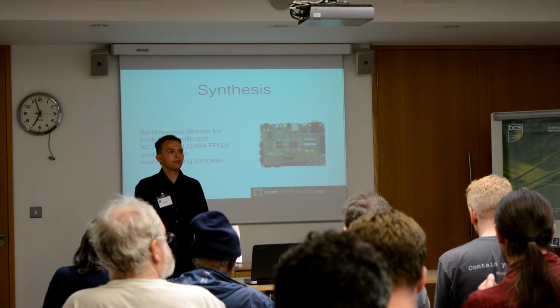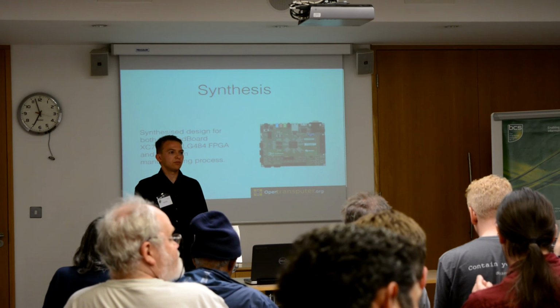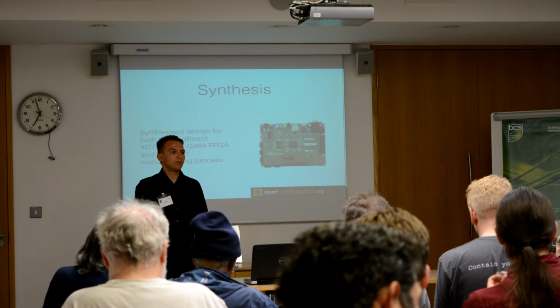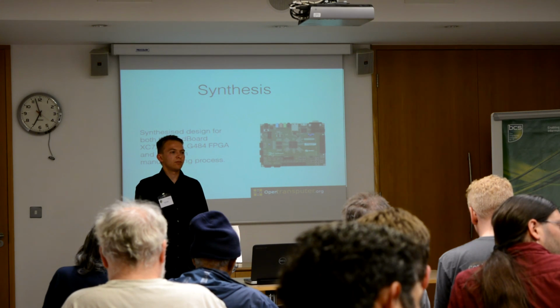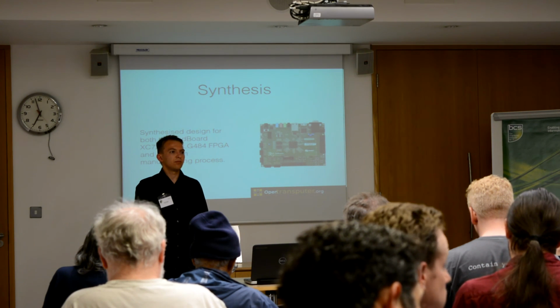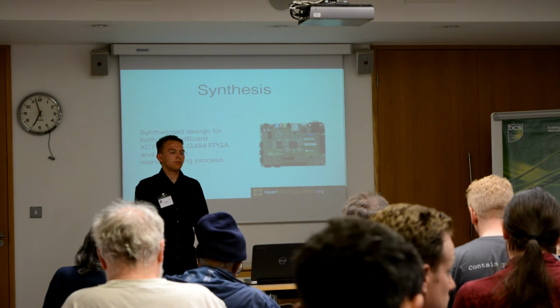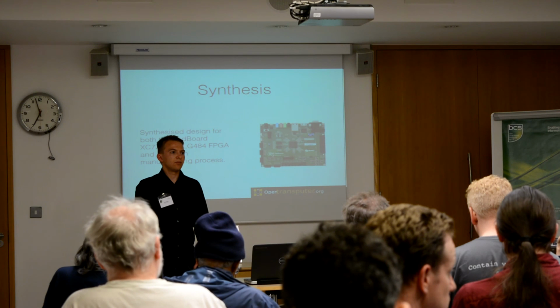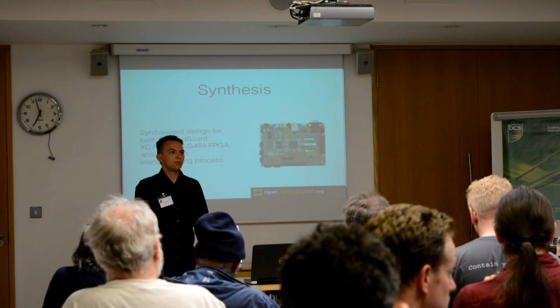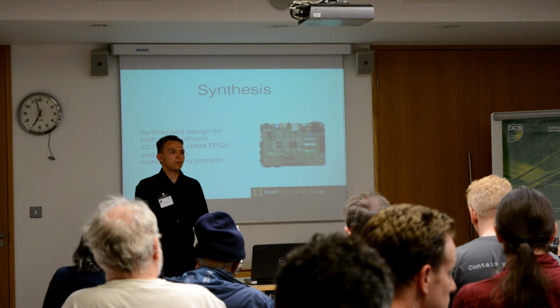Actually, I can help with that. He's referring to the registers that result from the fact that the Transputer has two priority levels, high priority and low priority. And the switch originally between high and low priority was done by dumping registers into memory and reloading from there. What they've done is to eliminate that overhead.